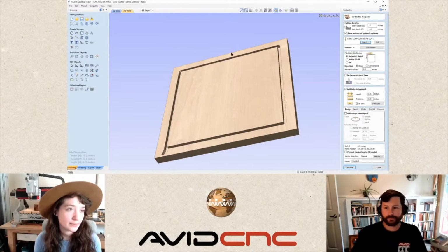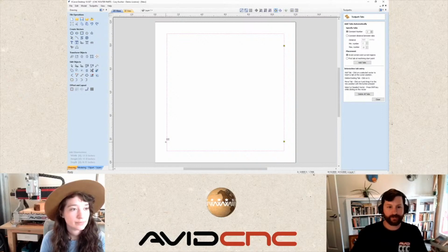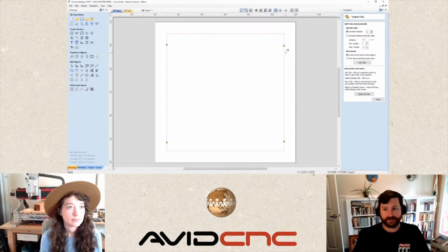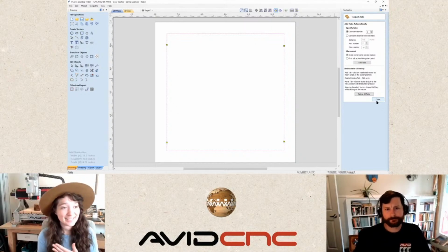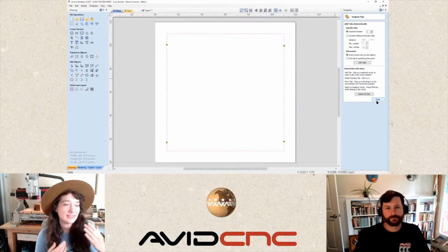in this circumstance. Yeah, so Sami's saying when we put them over here on the left and right, the grain is going to kind of cut through the middle of the tab and therefore make it weaker, because we want to look at the bottom layer of the plywood too. That's an important part here, is the bottom layer is what's going to kind of dictate where those tabs go in that instance. You kind of have to balance out how easy it is to remove, how strong you actually need it to be. You don't necessarily need a large bulky tab in order to hold this rectangle in place when you're removing it. It's a little bit of a balance between a risk analysis and how easy it is to finish later on.